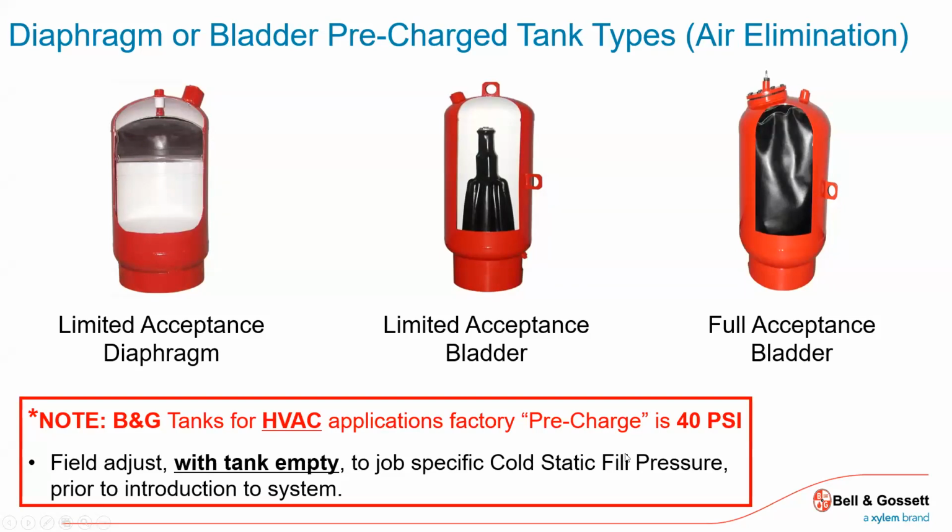I'm like, okay, well, how tall? Tell us the fill. Yeah, okay, we got the fill. All right, what'd you pre-charge the tank to? Silence. Oh, it's whatever the factory set it for. The factory has no idea where these tanks are going across the United States, to what buildings, the height, system height, where the tank is going to be. That's up to us, designing it, and then the installers to follow those directions to put it in correctly. So again, real subtle, so important. You just want to be aware of it.